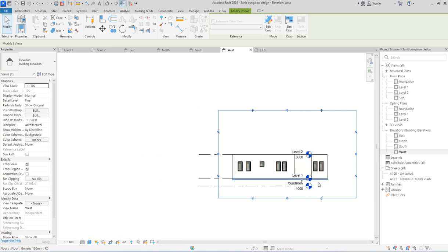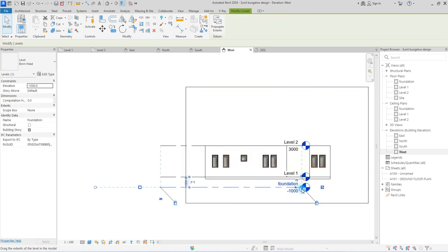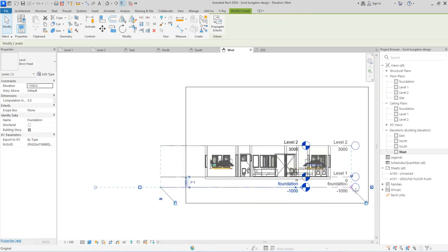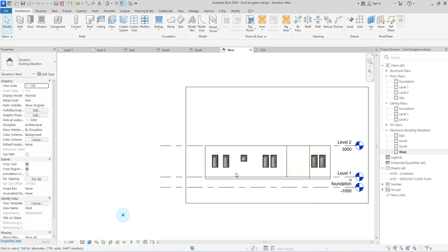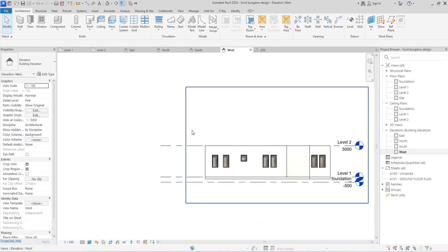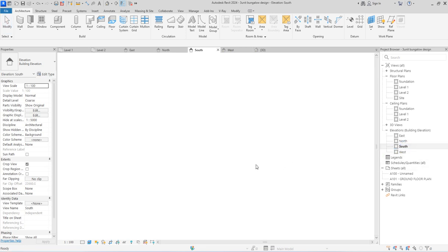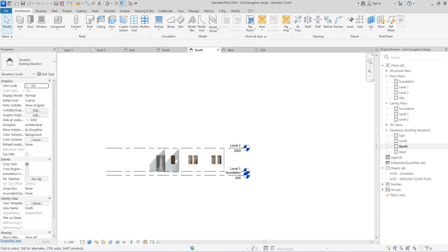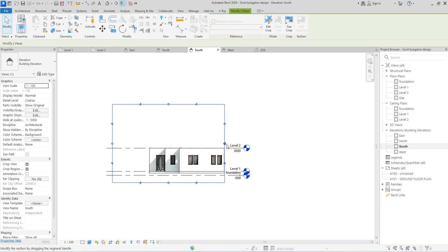So there's something I want to do to the foundation footing. Of this house is too high. So I'm going to reduce it to something that is appropriate. So let me just give it minus 500. I think it's okay. Good. So that will be the ID foundation footing. So then we go on and expand every other one that needs to be expanded.